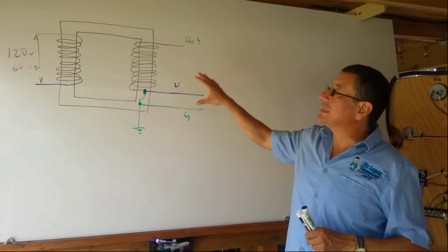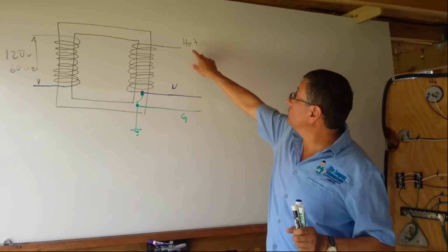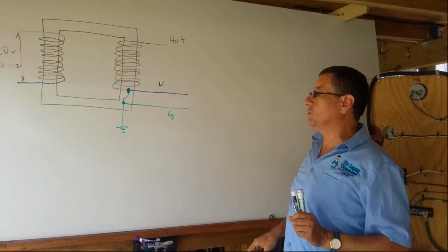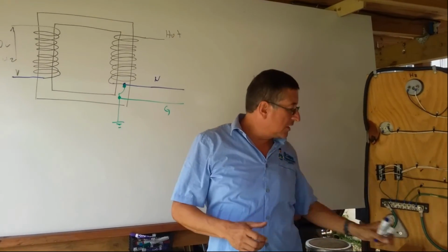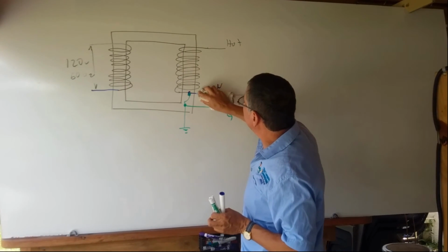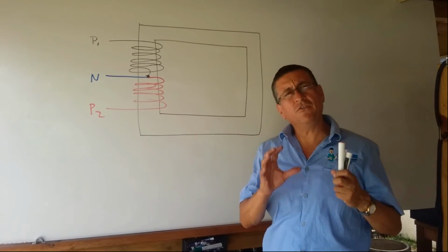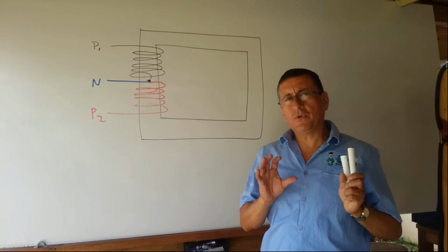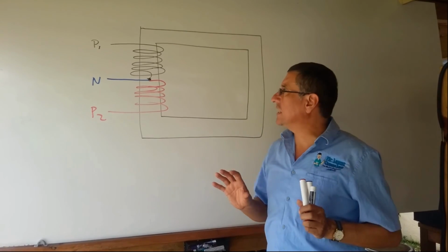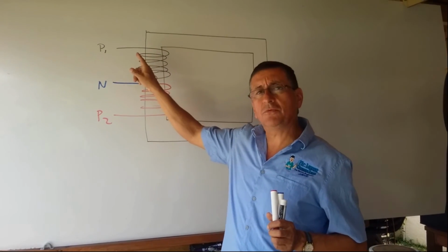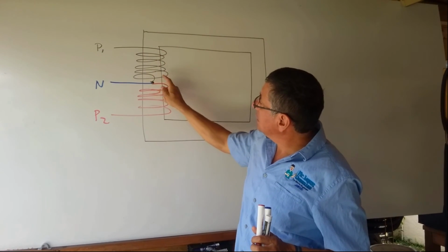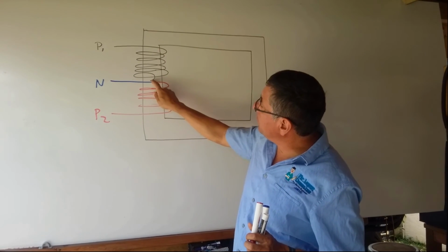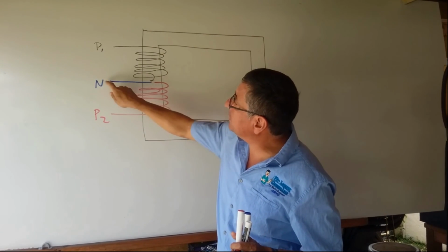All right, this is the procedure to connect a single phase transformer. And those are the lines, hot, neutral, and ground, that enter into the main panel and continue in the boat. Suppose that the transformer is not a single phase like this, it's a double phase transformer. If I have a double phase boat, of course I have a double phase transformer. The procedure to wire a double phase transformer is like this. This is the input. Phase number 1 is black color. At this point finishes phase number 1 and continues. But at this point, touch the frame and it is connected with the neutral.